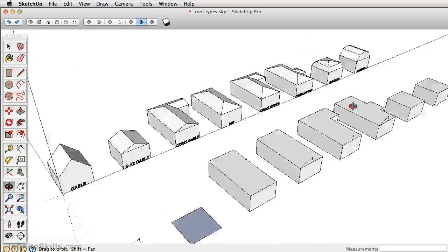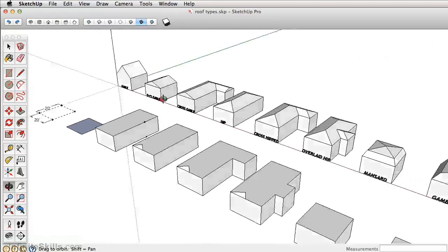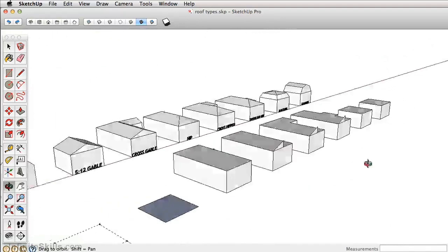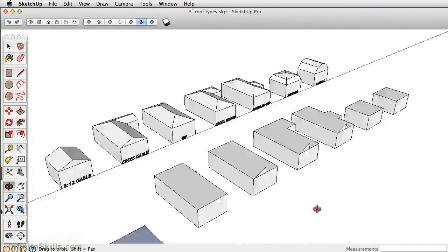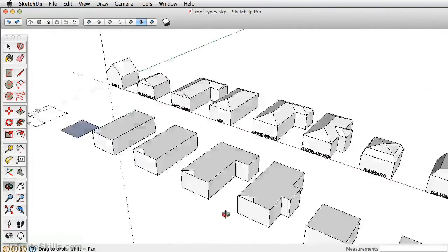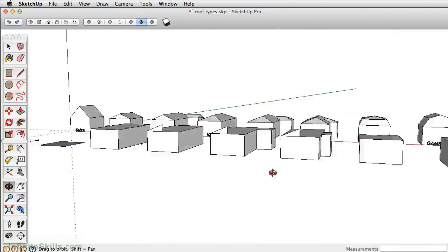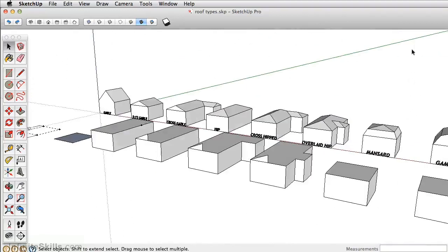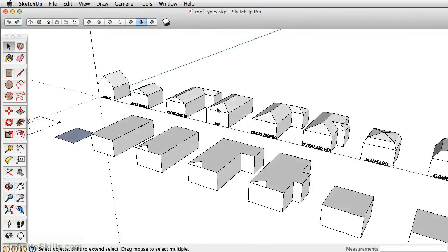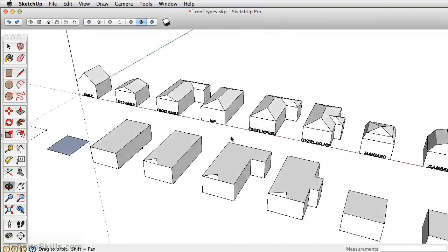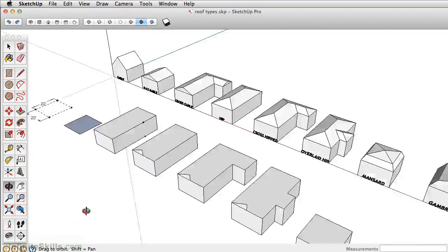Now if you're not familiar with 3D applications or you haven't been in a 3D program for a while, I find the easiest way when you're orbiting is to keep your cursor in this bottom range here, because you want to sort of turn around this area. Try to avoid being up here or up here. Either be in the center, or I find it easiest to orbit around this area here.